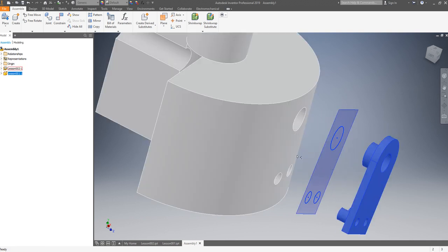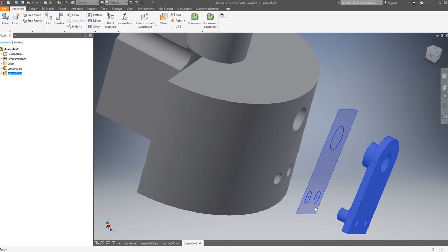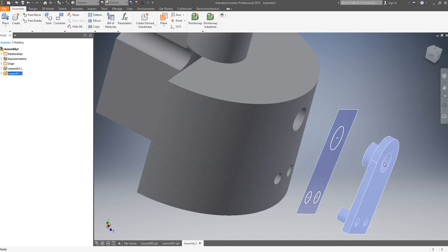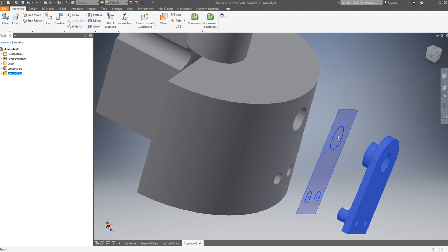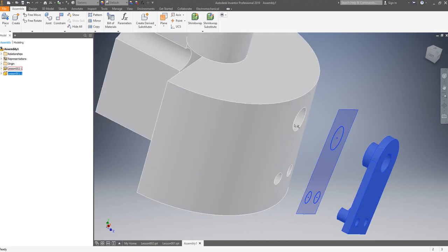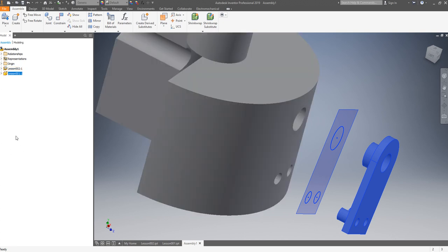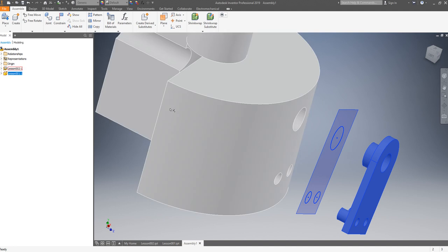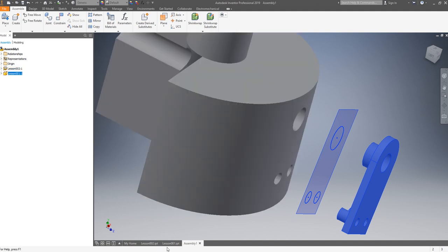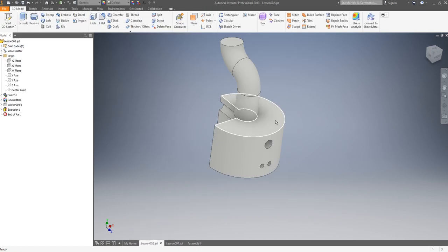So if we want to limit the rotation, we can draw some virtual or reference line here and the reference line on the another part, so we can make them parallel or angle as 0 degrees or 180 degrees as a constraint. Let's do it. So first of all, go back to the base, which is that.